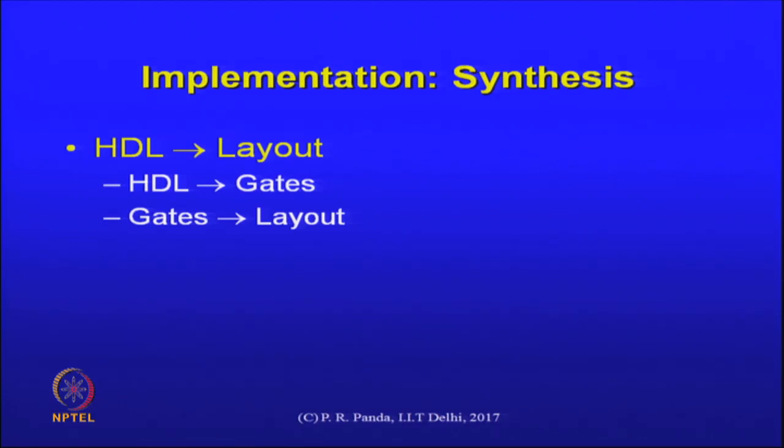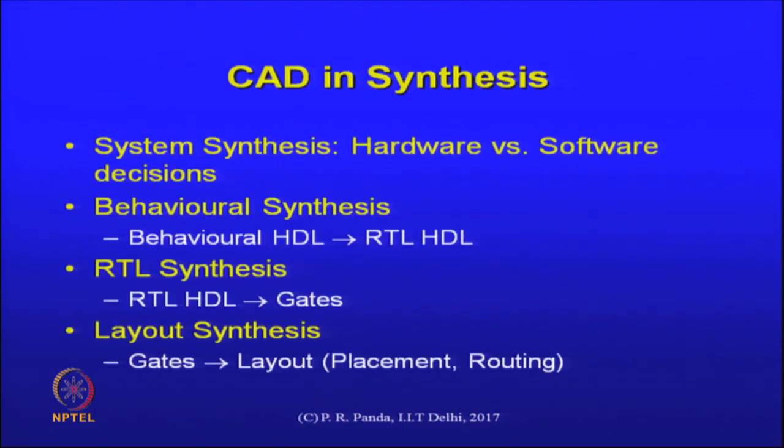Moving on to implementation, you have captured the intent in the form of an HDL and you have to go further, and ultimately we need to reach the layout. We can think of reaching there through a few different steps. So, initially I go through some set of synthesis steps that take me down to gates, and maybe at a later stage I invoke some other set of these physical synthesis tools to take me from the gates down into the layout. So, this step is what is called synthesis and is the focus of this course.